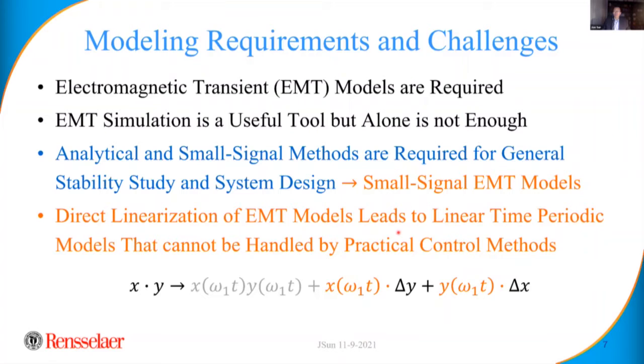And that's where one of the fundamental challenges kicks in, because when you try to linearize an EMT model, when you apply the traditional method, you end up with a linear time periodic model. And that model cannot be directly converted into the frequency domain to support the standard frequency domain analysis techniques.